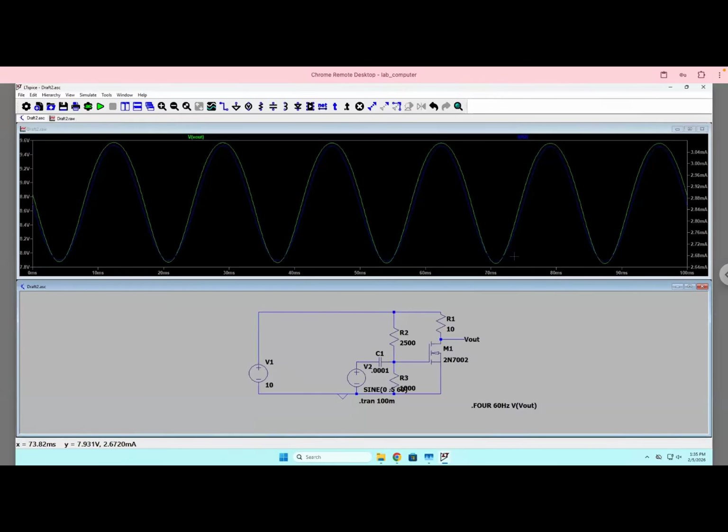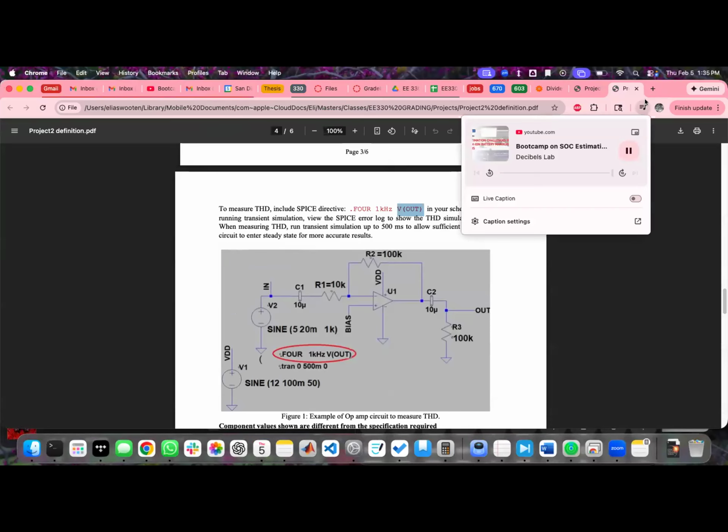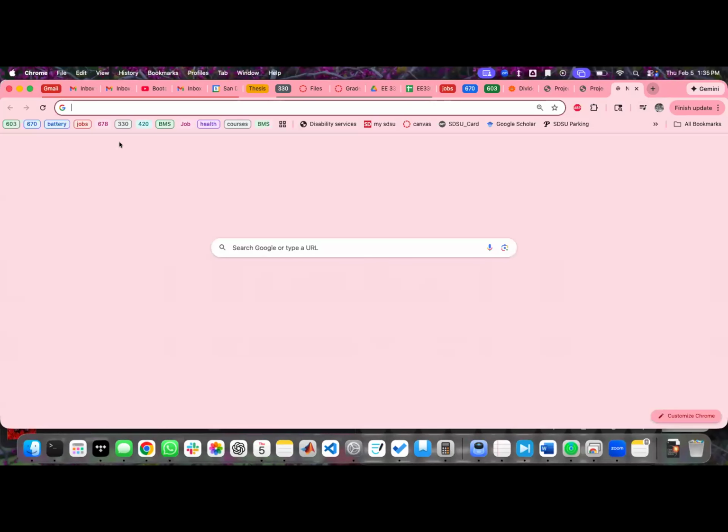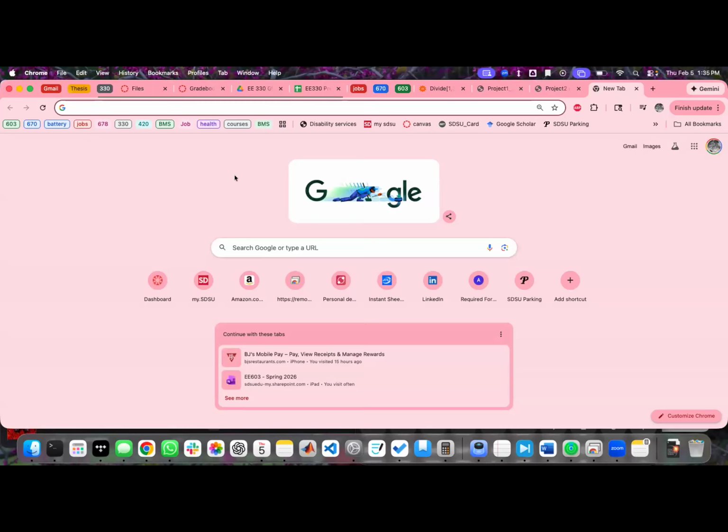The last thing I wanted to cover, there's kind of 2 things. I wanted to show you how to source a component really quickly, because it's not really something taught at the school at all, but it's really important. So there's really 2 tricks to finding components that work well. The first, which I'll show you in a second, is to filter by most purchased or most in stock on either DigiKey or Mouser. And the second is by looking at brand name, which you basically just have to memorize brand names. So the first one's way easier.